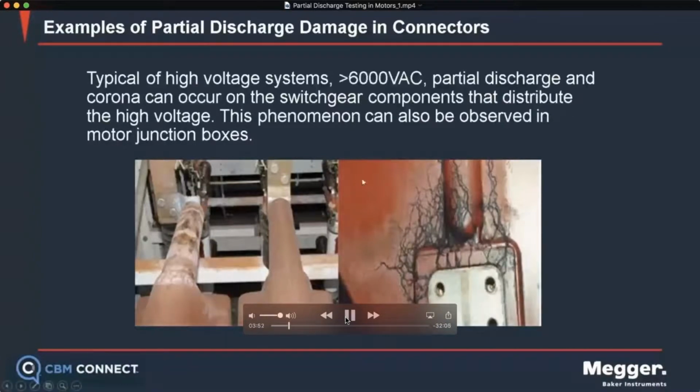And you can see this kind of unique powdery discharge, which is a pretty common visual cue that you have corona. There are white discharges and there are black discharges. I've seen both. Another observation that you might experience is the smell of corona, right? The smell that's produced during active partial discharge. So if you're in a room with a high voltage motor or high voltage switchgear that has corona activity going on, you can literally smell the ozone in the air.